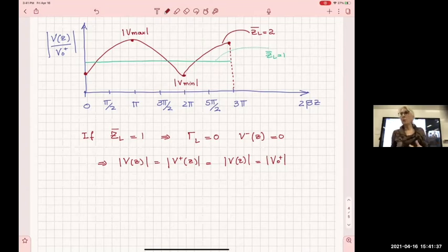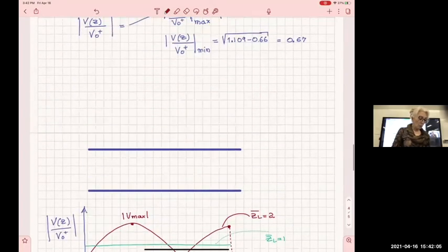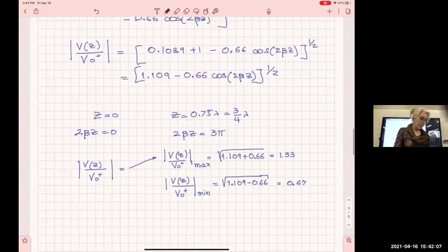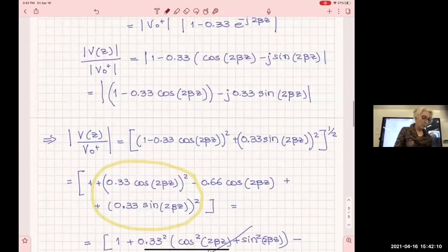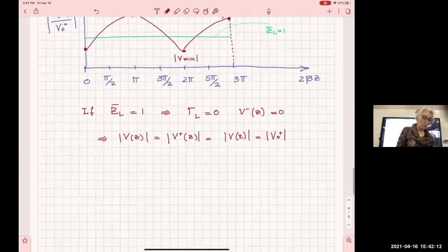All right, so the input impedance to an antenna is a real number, real in ohms. So I'm going to send all of my power to my load. Let's assume that this ZL was the input impedance to an antenna. Now it tells me that if this ZL normalized, my antenna has 100 ohm impedance, my transmission line has 50, then one third of my voltage is going to be reflected, and in terms of my power it is going to be 1/3 to the second power.